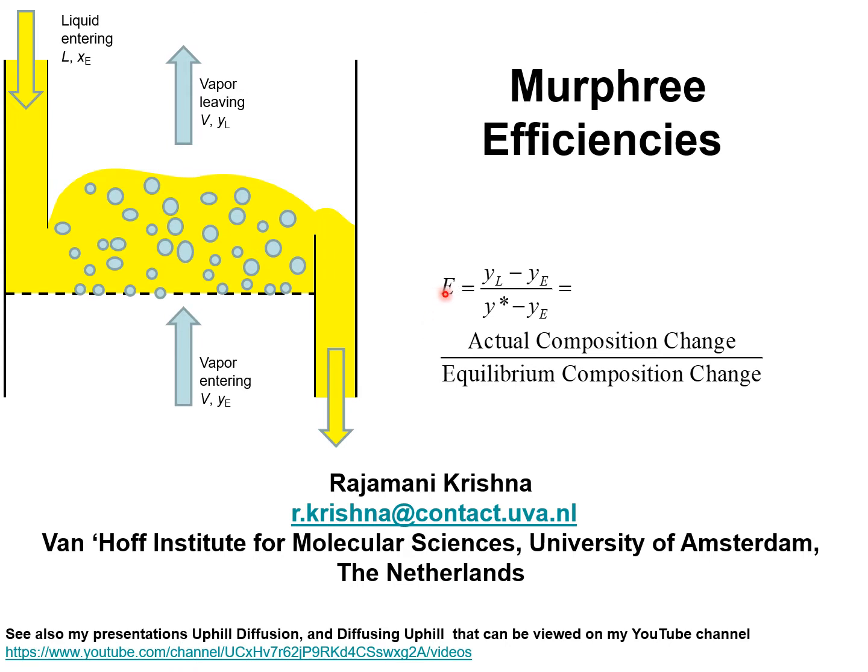The Murphree efficiency for the vapor phase is defined as the actual composition change divided by the composition change at equilibrium conditions. In other words, if the vapor leaving the tray was in equilibrium with the liquid on the tray. And the equilibrium composition is Y star. For a binary mixture, since the mole fractions add to unity, the Murphree efficiency for component 1 equals that of component 2, and both these efficiencies must be bounded and lie between 0 and unity.